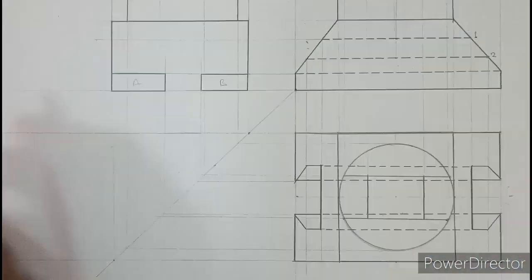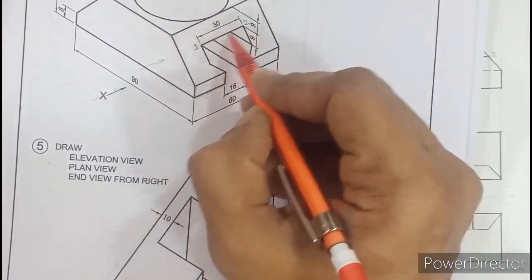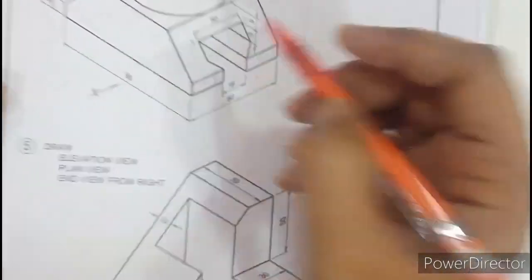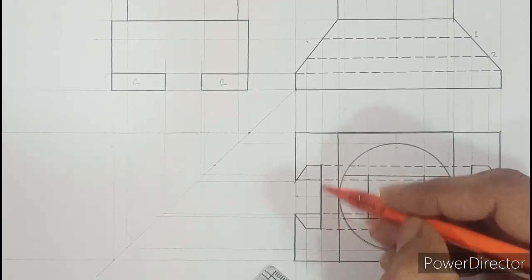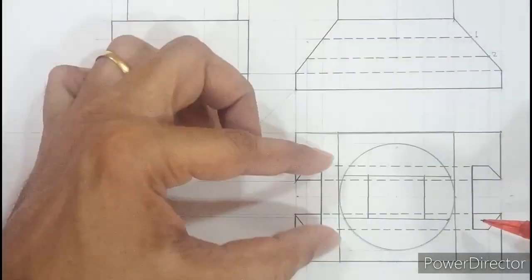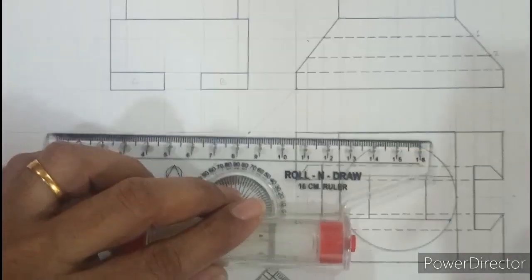here. See, one can easily measure 30 and draw a dark line, but here this 30 millimeter you need to recognize where it is in the top view. So in the top view, the same 30 is this dark edge. So I hope all of you can see that 30 mm, or you can see on this side, this is that edge of 30 millimeter. So that 30 I need to project till 45 and extend it above. So from here, let us do that.